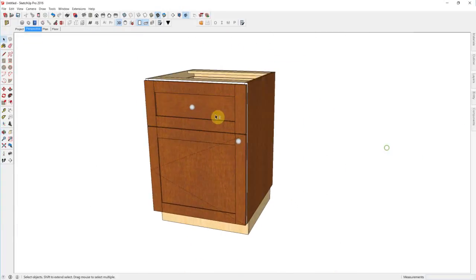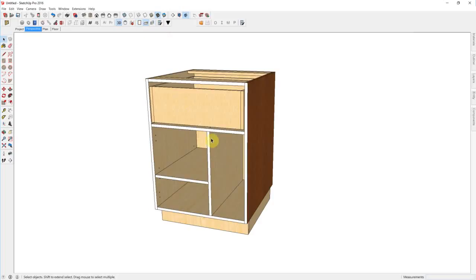Okay, so whatever you put inside the carcass is what gets copied onto your actual cabinets. So if I didn't want to have any control over my partitions, i.e. any cabinet I brought in, just use the partition from the cabinet, and I didn't want to impose any structure from my template, I could simply get rid of my partition.